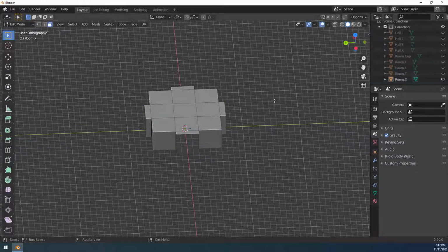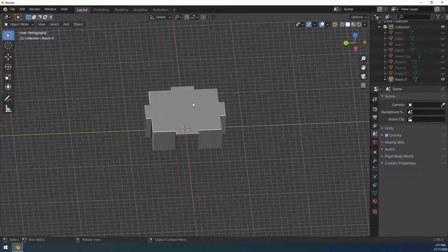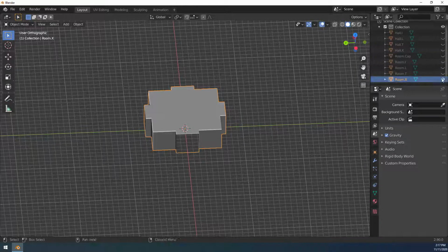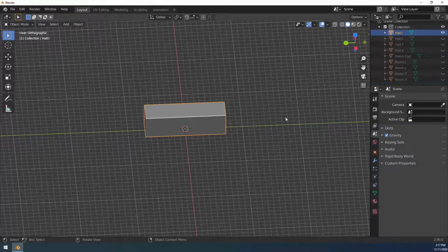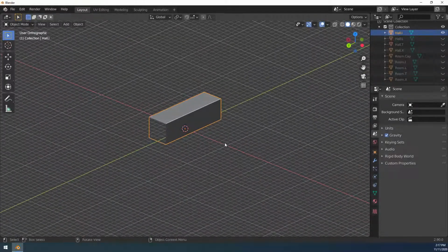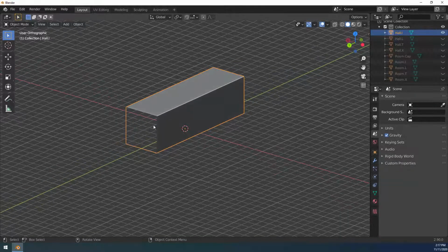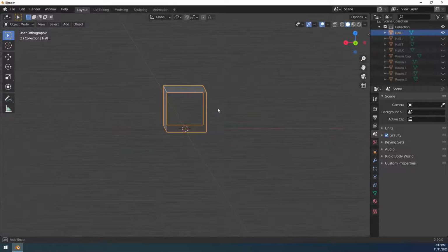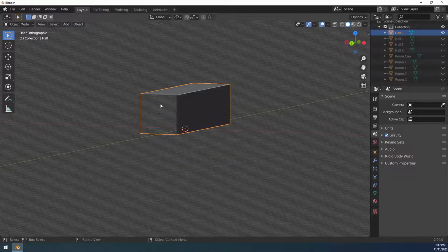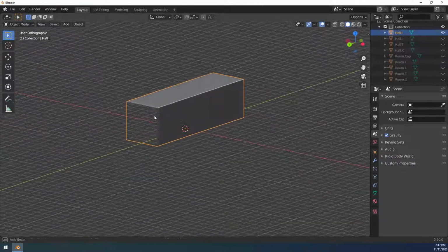And you'll notice that because of my naming conventions, you don't even have to see what's going on over here. You can tell what each one of these rooms is and what it looks like just by that naming convention alone. Let's go and add a little bit more detail to this. We've got a little time here. So what I want to do is add a little bit of heightened ceiling in the middle, not perfectly lined up with the edges, but sort of inset into the geometry of the room. And then finally, we're going to invert these so that all the faces are on the inside. So that if you were standing inside of this thing, you would see faces. Right now, you can see through it, and we don't want that. So we want to invert this.